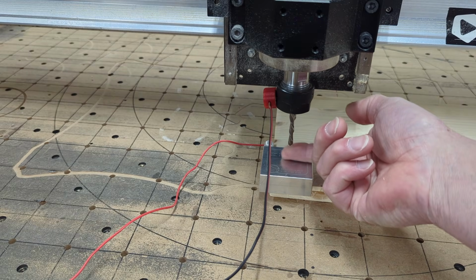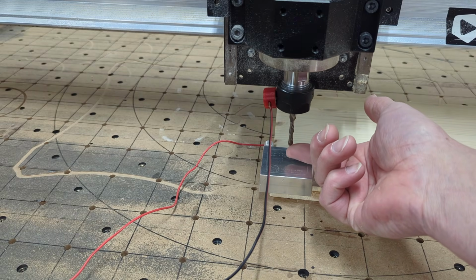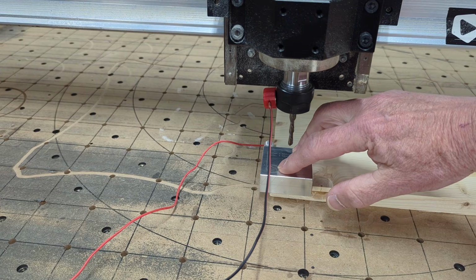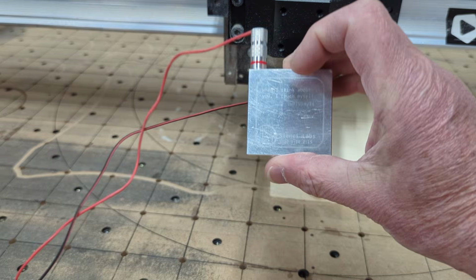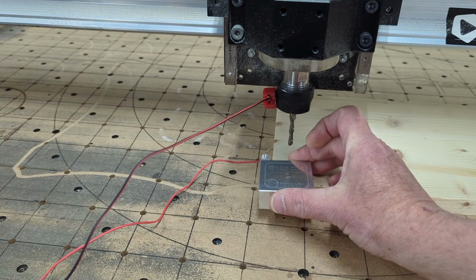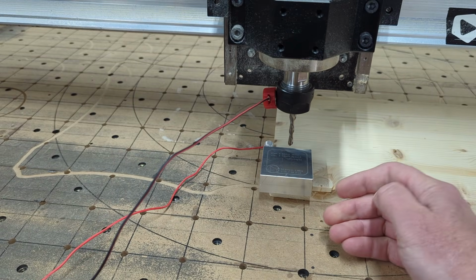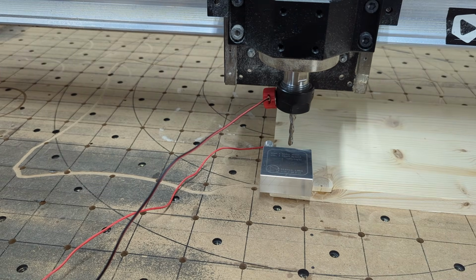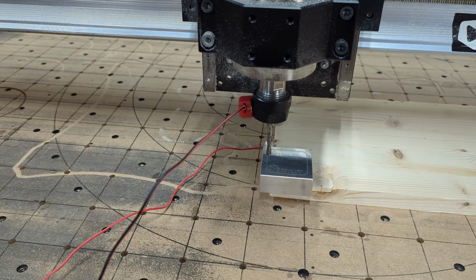Now I need to move this down. This needs to be relatively close, within 1/4 of an inch of the plate. And we also want to move it over to this circle that's on the plate right there, because the Gsender software, when we set the 0, is programmed based on that center point. So you simply want to move that over into that area, and we should be good. And we want to move the Z down.